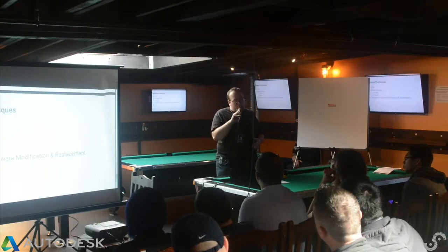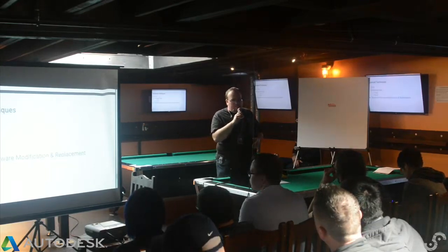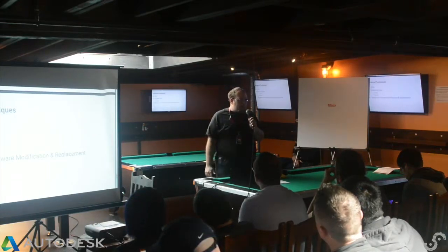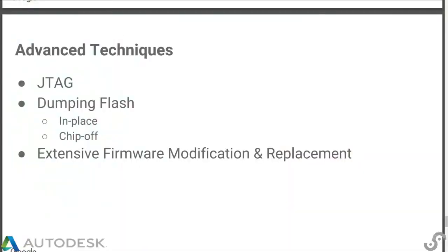But we had a little bit of a problem when we tried that. So I mentioned modifying the binary. It turns out that this particular device uses a file system that compresses all of the files, which sounds great. You want to use as little flash as possible, sounds great. I modified the binary. I put some NOPs in place of actual instructions. The binary was exactly the same size, byte for byte, and then I tried to write it to the file system, and it says no space left on device.